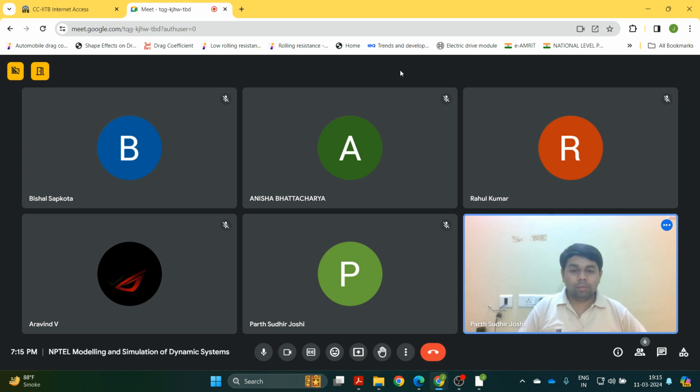And then we have again hydraulic and pneumatic systems, where basically fluid power is being used. In hydraulics and pneumatics, the essential difference is in the working fluid. In hydraulics, generally oils are used, or basically liquids. So those are basically incompressible fluids, whereas in pneumatic systems, the fluid is generally air, or basically a gas, which is a compressible fluid. So again, the behavior of these hydraulic and pneumatic systems can be represented in terms of capacitors, resistors, and inductors.